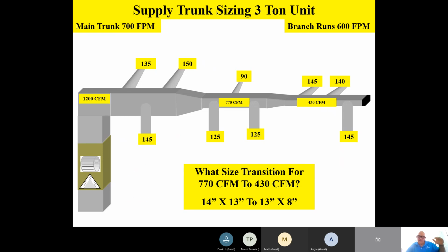So the next level of figuring airflow in each space or each takeoff was what we call the cubic foot method. What we did there is we would calculate the square footage. In our example, a 10 by 10 room is 100 square feet, and if it had an 8-foot ceiling, that would be 800 cubic feet. Then we took that 800 cubic feet and multiplied it by our ASHRAE recommendations.